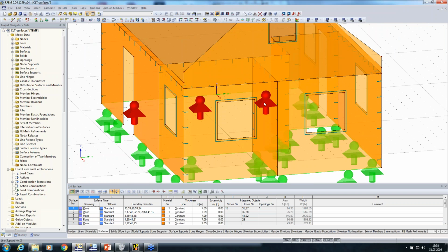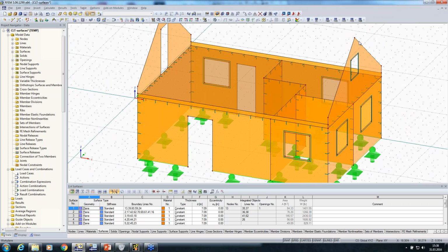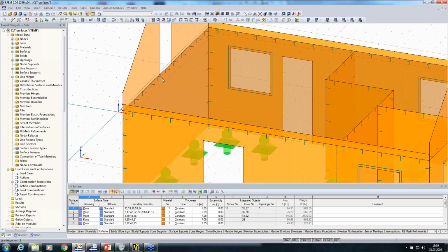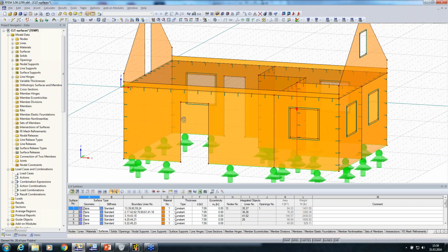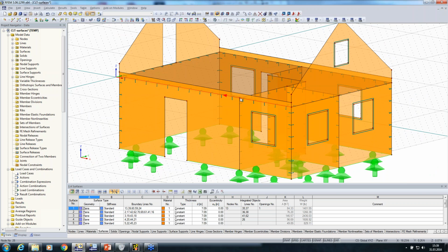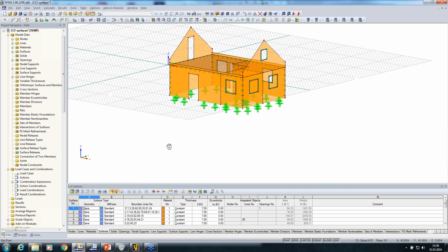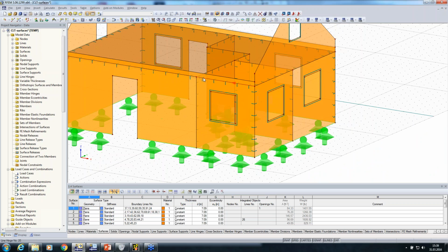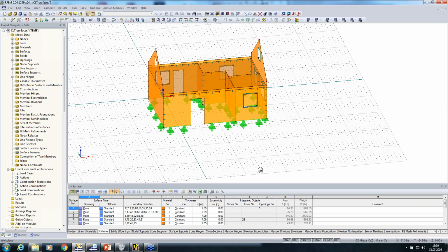Let's assume that it goes continuous from the bottom to the ridge right here, and I do the same here as well. One thing I just recognized right now is that it's not cut. Here you see that this node is not integrated into this line. That I'm going to do via this command. And when I go on the line right now, you see that this is working.